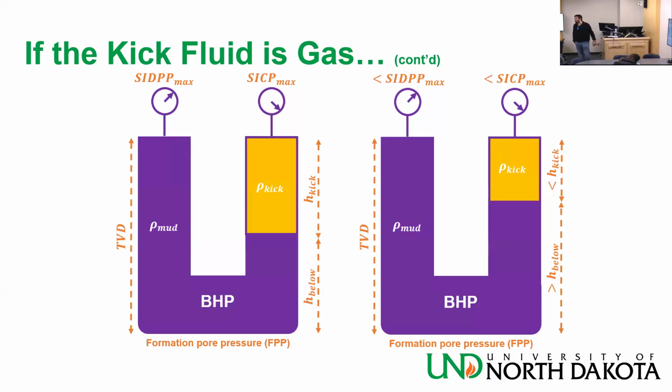Now, what they do normally is that they drill the whole vertical section without even cleaning the mud sometimes, just recycling the mud. Bypassing the shale shakers, bypassing everything, it goes directly into the mud pit and then back into the well.